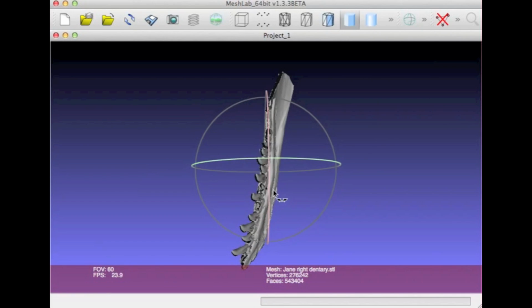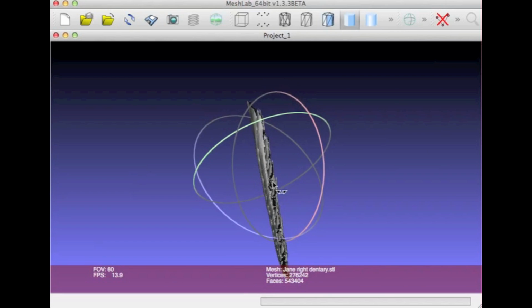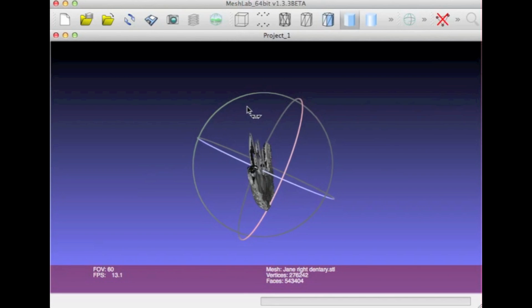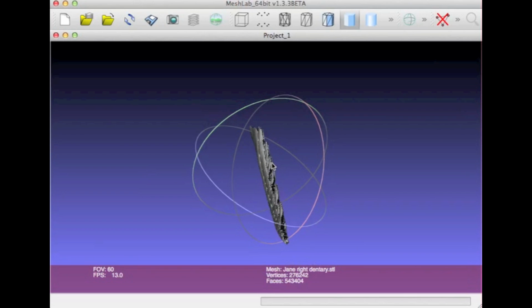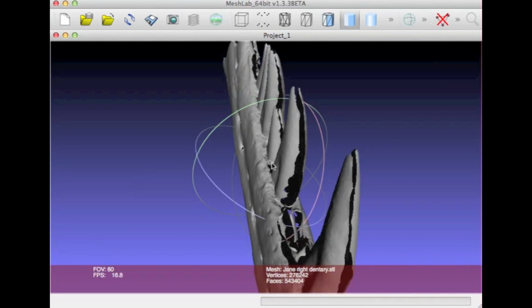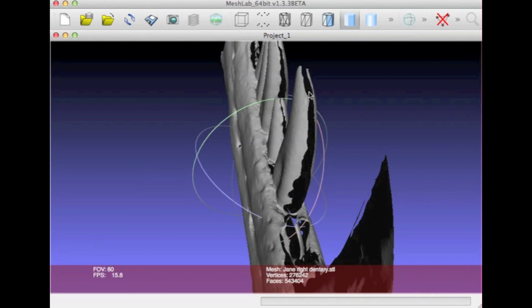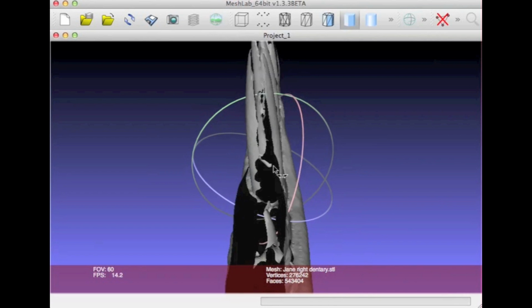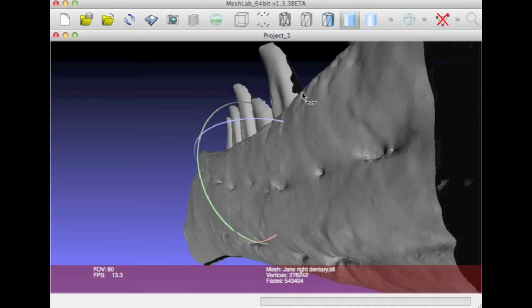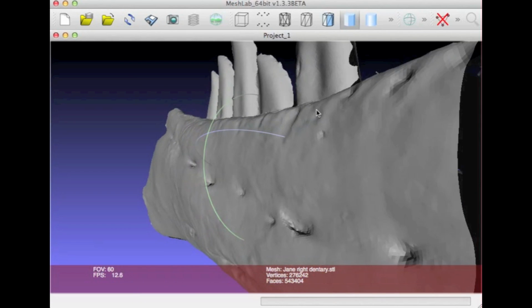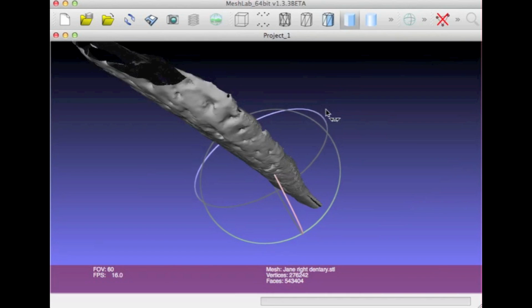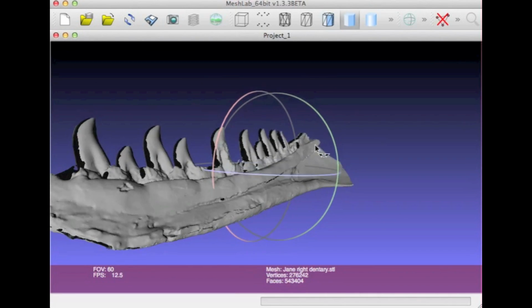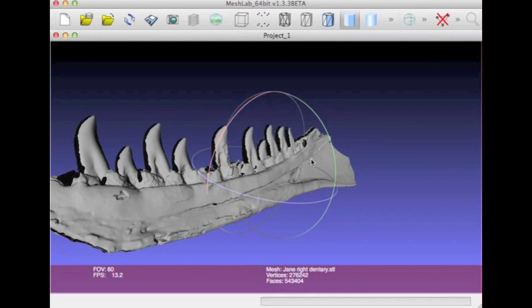We can see off the bat from spinning this around that there are some flaws in this mesh. So I go close, and these black spaces here, these are holes in the model. If I were to actually cut this up for printing, these areas would not print, and I'd end up with an unstable model and an unsolid model. So it'd only print the outer layer.